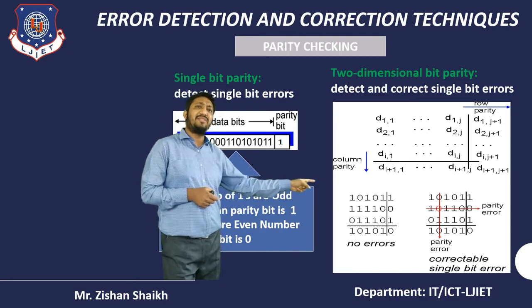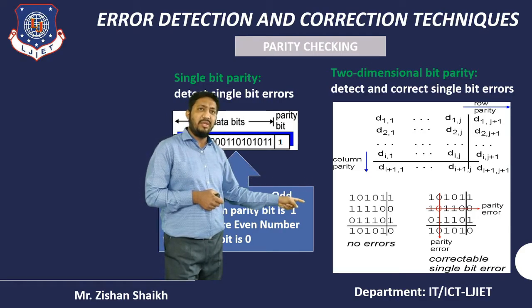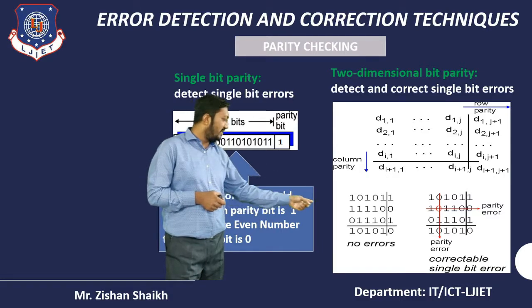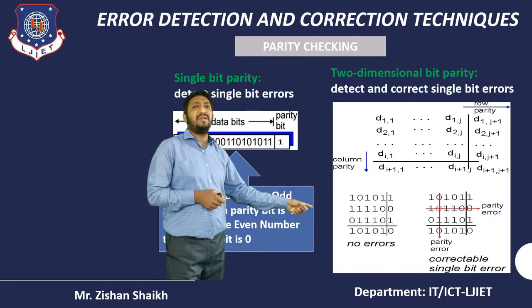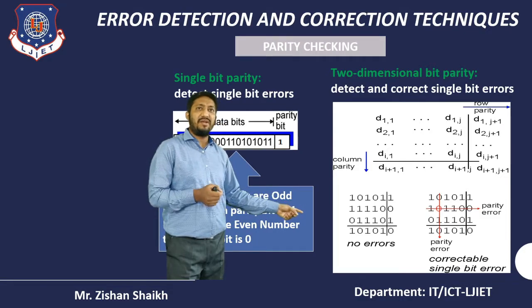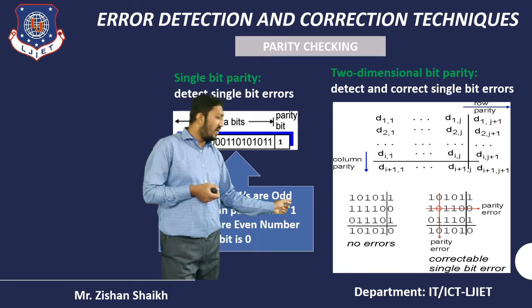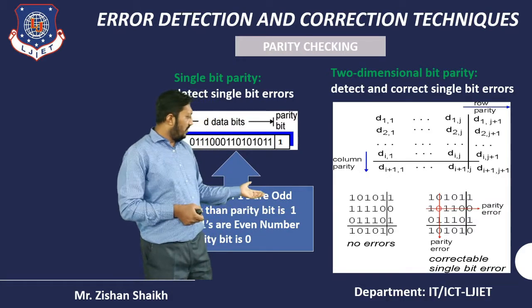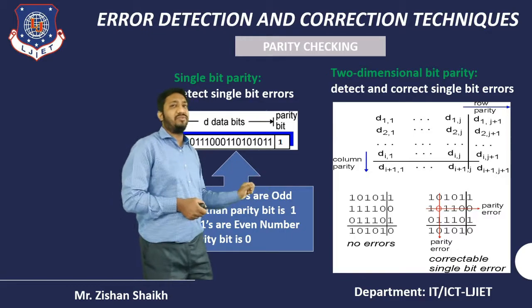So at the last, our parity bit will be 0. For the third row, we can see 0, 1, 1, 1, 0. So how many times is 1 coming? 3 times. So in the last column, we put the parity bit as 1, because the number of 1s is coming 3 times. So we are counting this parity row wise, but now we are putting it column wise also.